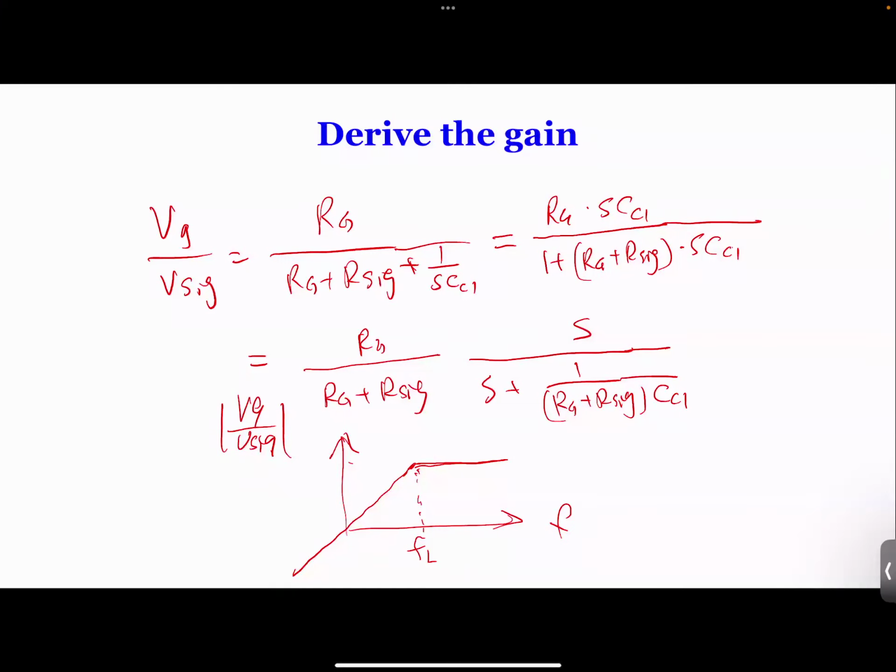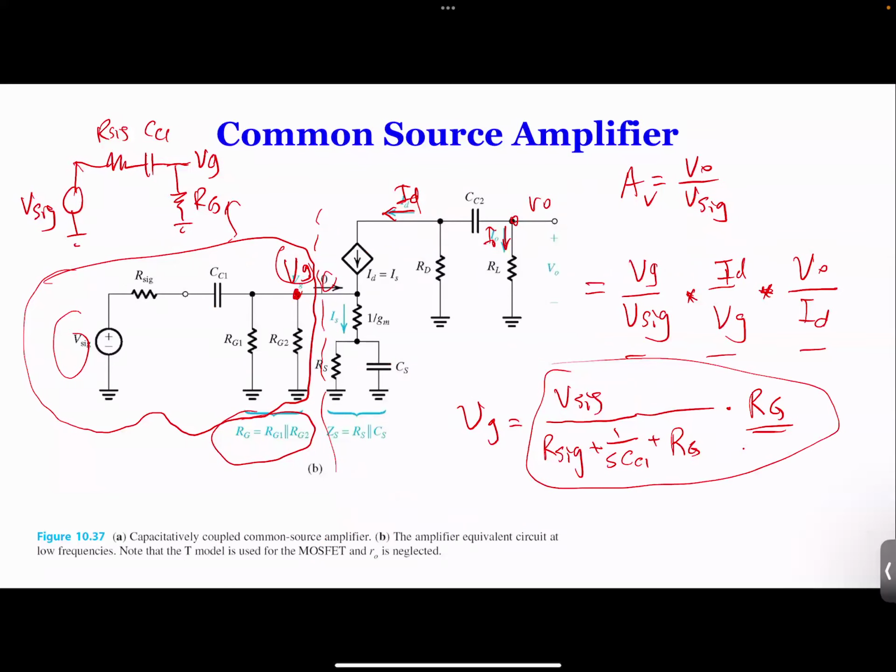For what kind of voltage would you have S equal to 0? DC? Yeah. So if it's DC, now you go back, you say, oh, for DC, what happens? This is open circuit. This is open circuit. Nothing is converted. So this here is nothing. So it's open circuit. So that's why for DC, the gain is 0.